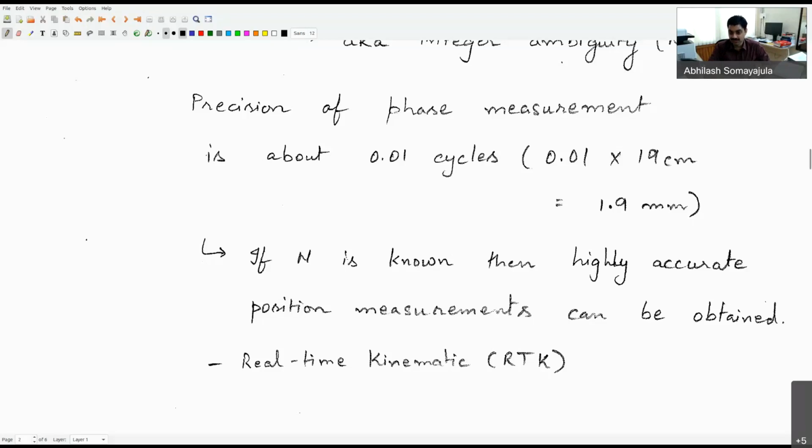Because the time delay will be different for each of those paths, which means you will localize yourself to be somewhere else. You're presuming that you're looking at a straight line between the satellite and you, but that need not be the only path through which you're getting the signal. So these carrier-based phase difference-based methodologies are not as robust as what you see from typical differential GPS systems.